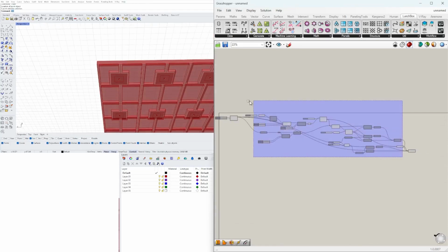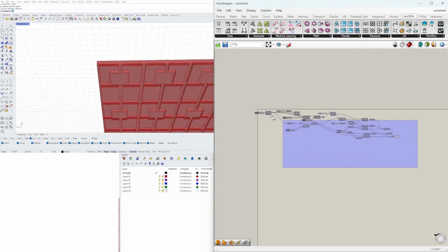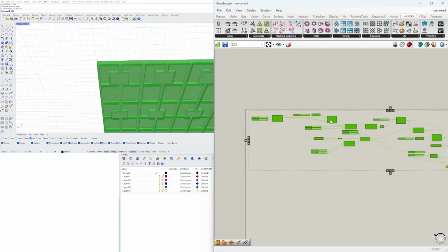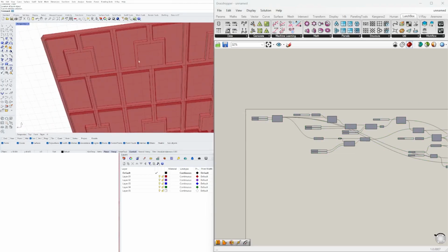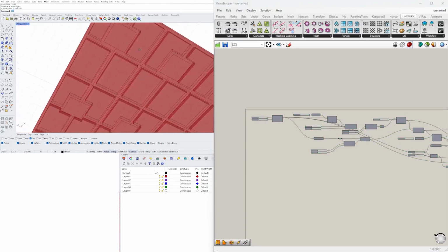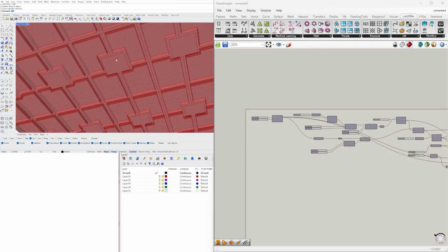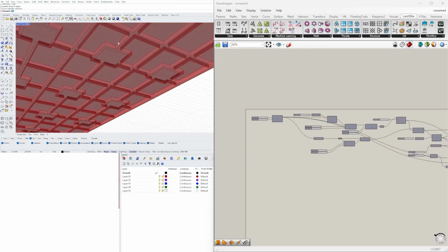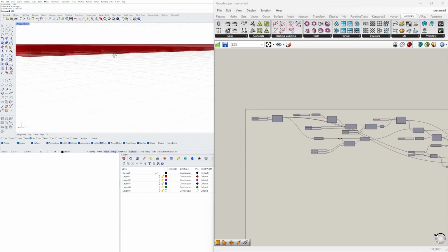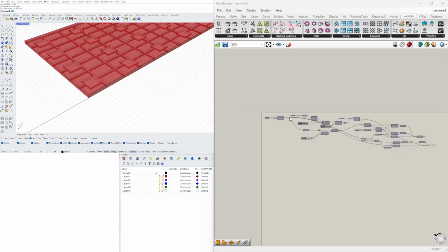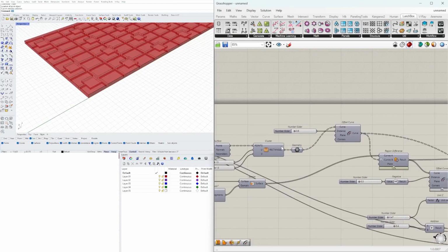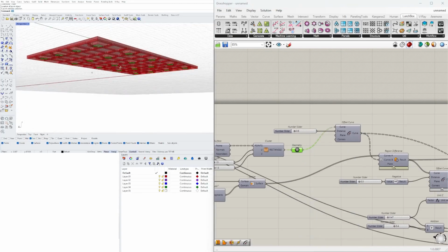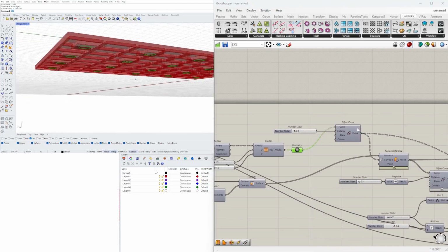So the cool thing about this, and I know there were some places where I wanted to show you something else, but I still have to figure that part out. The important thing is we have the location where the slab or where the column touches the ceiling. Then the subtractions for the waffle slab, and then at the top, it's going to have the thickness for the floor slab. So let's go and take our original rectangles and extrude them down to create the columns.